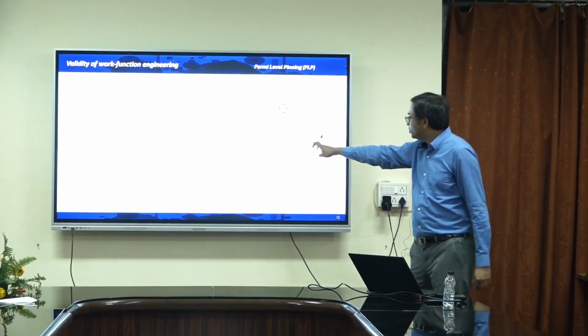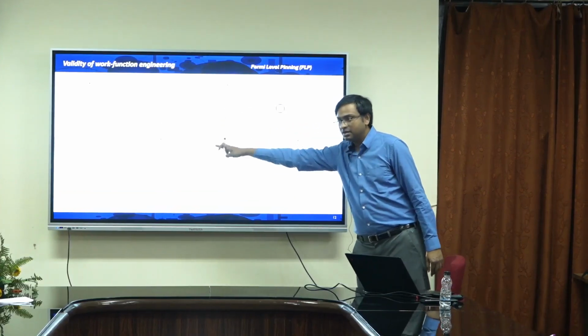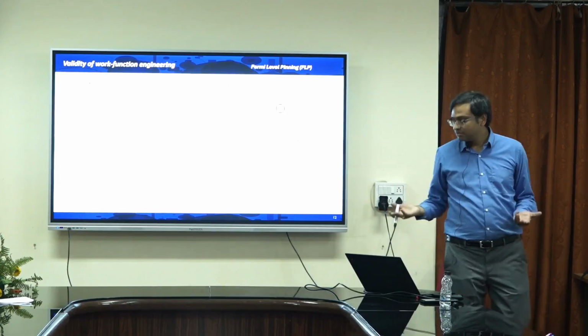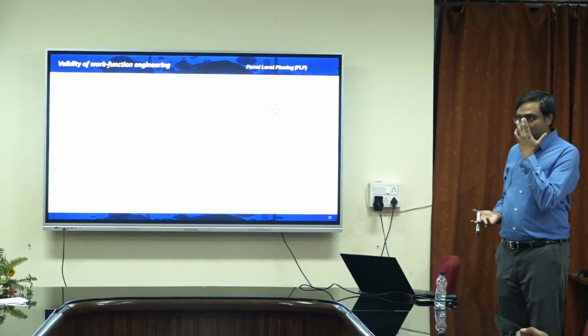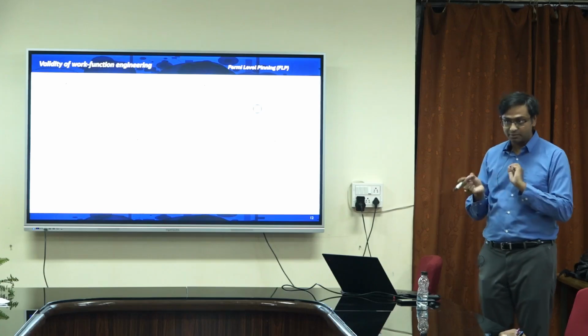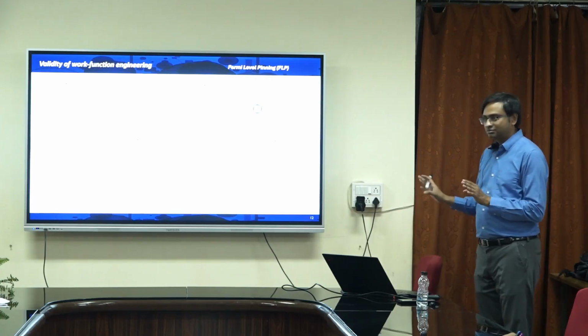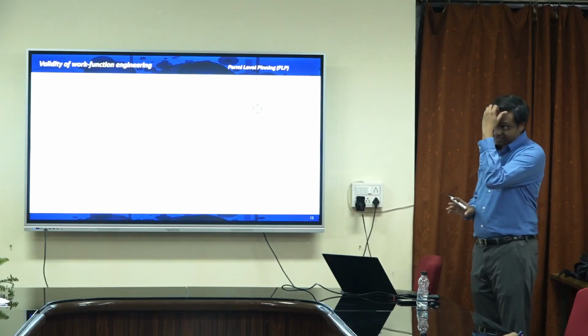A small work function metal takes me below 0 for n-type, and a large work function metal takes me below 0 for p-type. So choosing the right metal becomes important to get ohmic contact for both n and p. This is established. It is material specific.